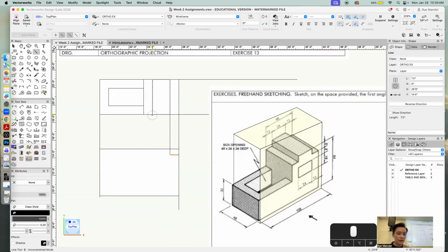So same thing over here, right? I can just draw this line that brings it down. I can do 8 inches. I'm hitting shift so it snaps at 8 inches. And then I click. I know this is another 12 inches when I'm drawing this because over here it has a 12. So then I move in the direction that I want, type 12 inches, hit shift so I know it's clicking in a straight line, and then I click again. And that's how I know I have that.